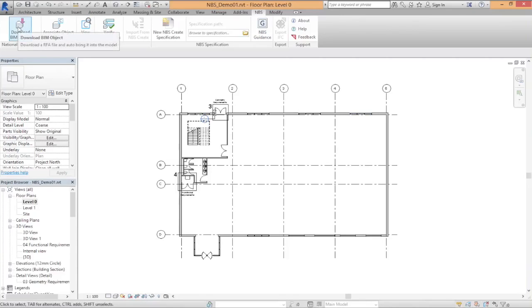Now, traditionally with CAD, you would draw lines and shapes, and you would form elements such as doors, walls, roofs, windows, and you would create those just by simply drawing them. And with BIM, yes, you have to create doors and windows and so on, and ceilings, but you create them as objects, and these objects know what they are. So a door knows it's a door, a window knows it's a window, for example. And these objects then behave in a particular way. So you can place windows in a wall, for example, but you can't place a window in a door.